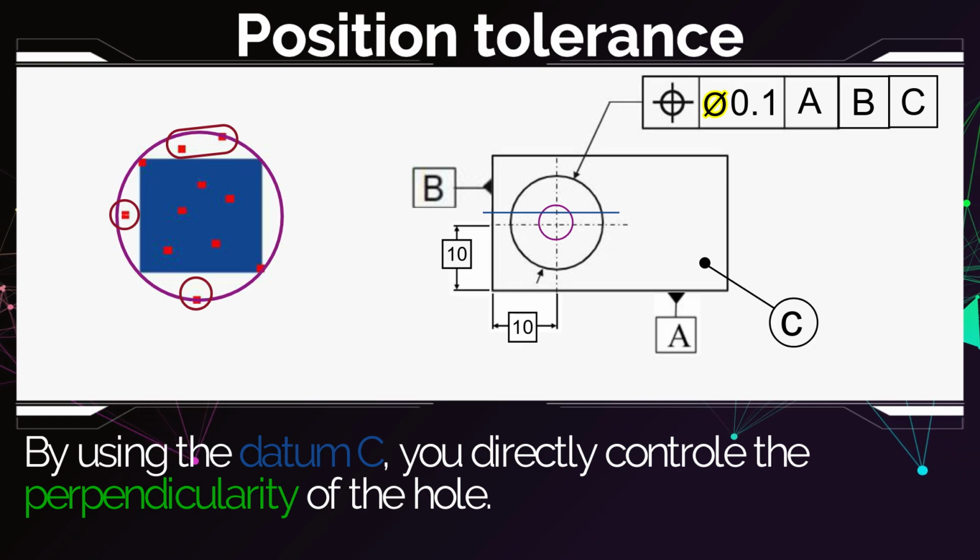Usually for your function, what matters for a hole is the radial distance of the deviation from the ideal center line. If you had to look at the point that lies here or there, you accepted them in the first tolerance, which was 0.1 using normal plus and minus tolerances. Although they actually have a radial distance to the center of the hole of 0.141.